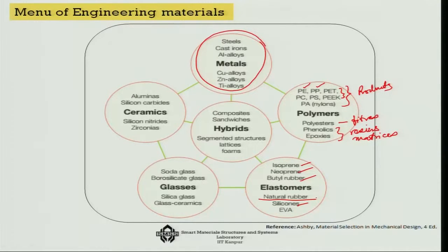is that if you think of metals, for example, I will talk about this later on, but maybe I will just introduce at this stage that if you look at the stress strain diagram for the metal, you would see that it goes straight, elastic and linear, then it actually has a yielding and then it goes down. And this linear level is generally about 0.1%.